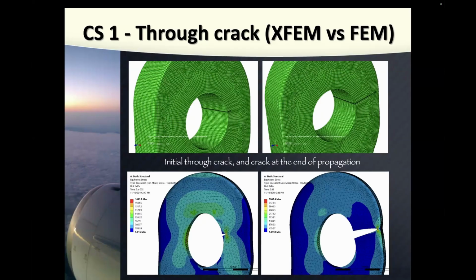What is one of the disadvantages of ANSYS? You can use only tetrahedral mesh here. But the reason is simple. I proved that tetrahedral is better in XFEM too. So you cannot create hexahedral here, only tetrahedral mesh. So they learned probably from some examples, maybe they read my papers. I don't know. I'll ask them next time.